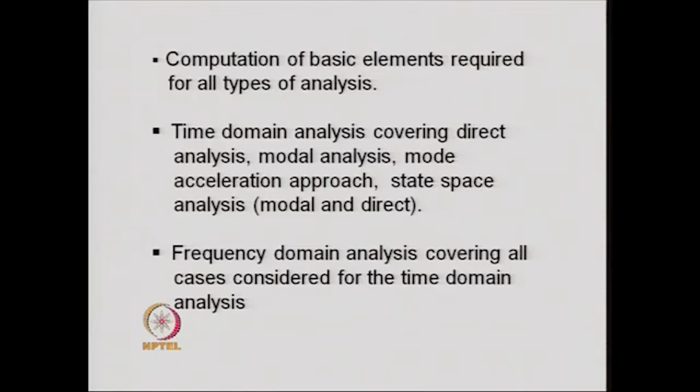Then one can obtain the quasi-static analysis of the system for the ground motion, the mode shapes and frequencies, and for each mode shape one can also find the mode shapes for the bending moment, shear force, etc. All these kinds of computations are contained in the first part of the program, and the results can be stored.